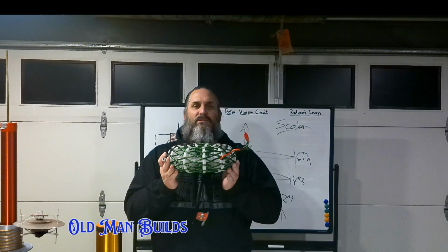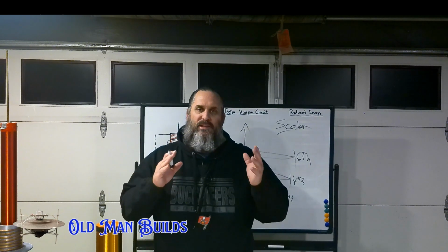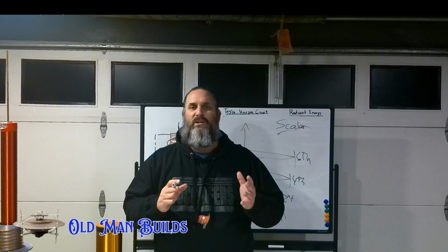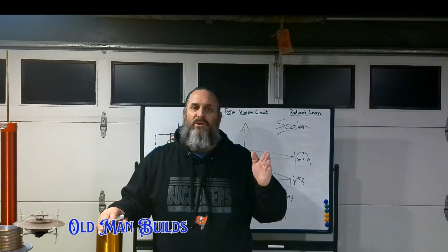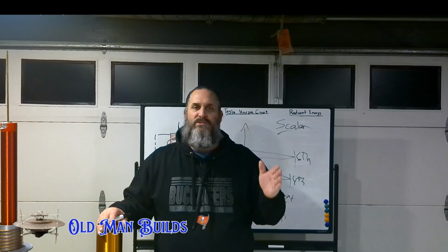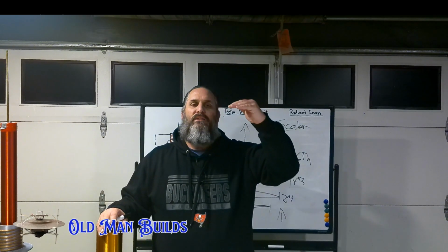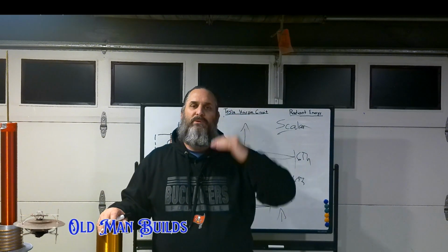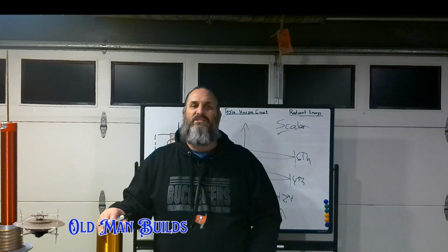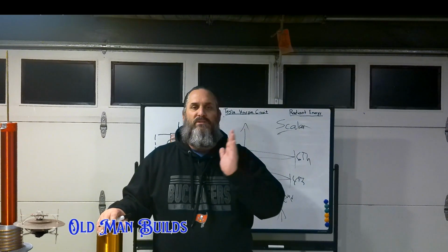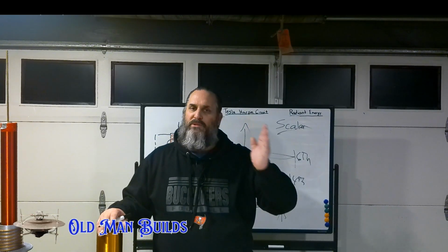This stops that. It stops it dead in its tracks. So when I take a number 2 coil and I have it connected, I need to create that same break. But I must compensate for that in the system. Anytime that I add that to the system, I need to compensate because the amount of copper in that coil changes. You see, I'm changing the capacitance in it. When you change the capacitance in it, you're changing the frequency. Therefore, you must absolutely 100% compensate for it.